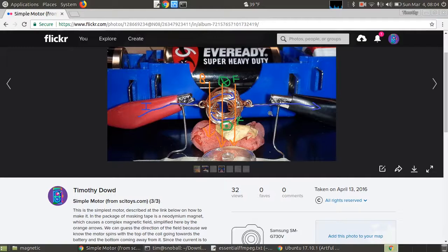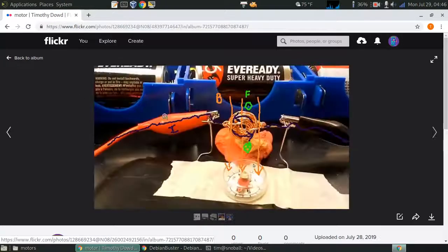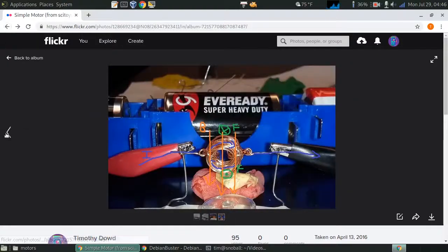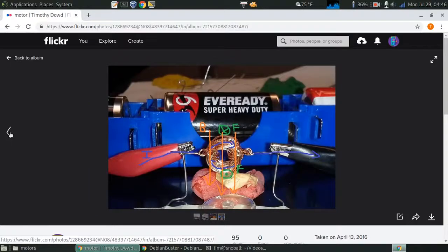So there's one final issue with the motor. If the coil is set up at first so that the current is going in a clockwise direction like this, so the right up top and the left on the bottom, it's not going to stay like that. As the bottom comes towards me and the top goes away from me, it's going to flip. This bottom piece will move up and become the top piece, resulting in on top the current will go the other way. That will reverse the force too. And what's going to happen is as the thing rotates, the two situations are just going to go back and forth with the force constantly reversing. Let's see what that looks like.